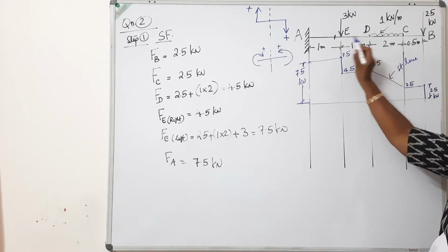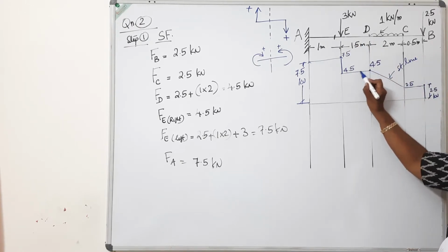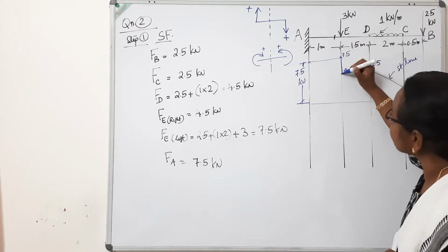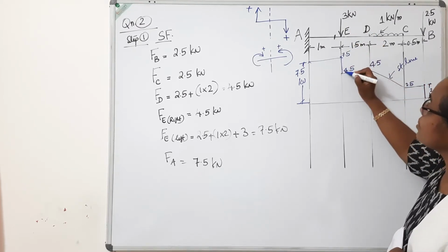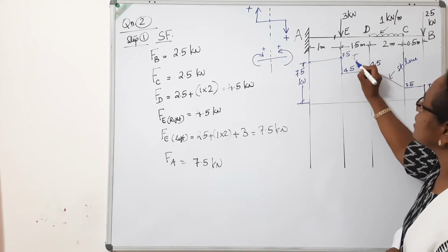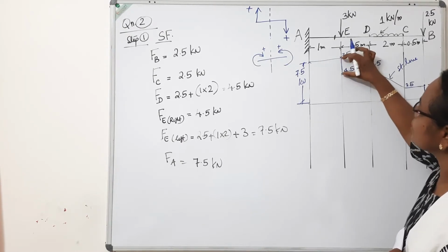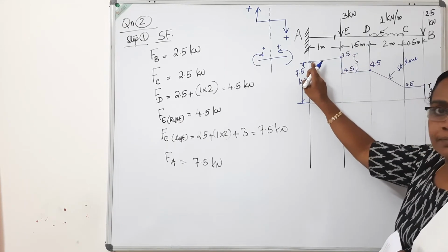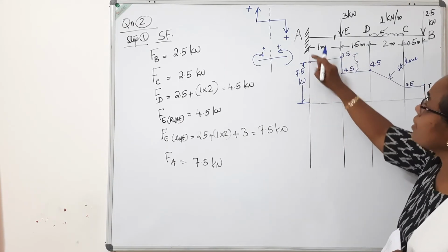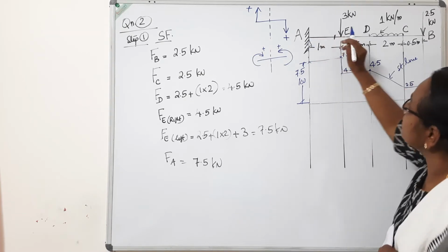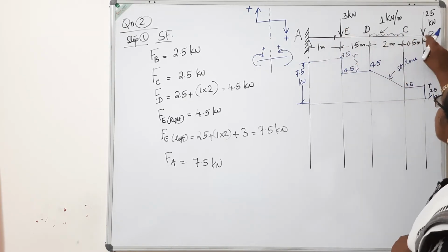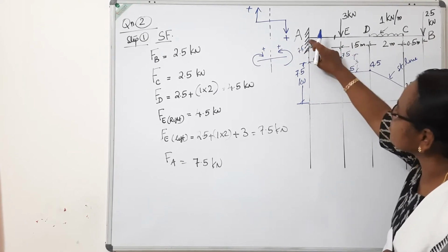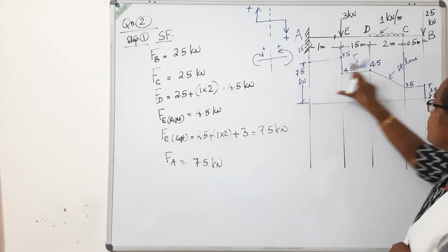And there is no load in between these two portions. So come to 4.5, come parallel to this. Then suddenly there is a load of 3. So increase it by 3, raise it by 3. So it is 7.5. So this ordinate is 3, this vertical ordinate. There is no load, so you just go straight. And this is 7.5. See, the reaction at this support is going to be 3 plus 2, 5, 5 plus 2.5, 7.5. So this vertical ordinate represents the reaction here. So this is the shear force diagram.